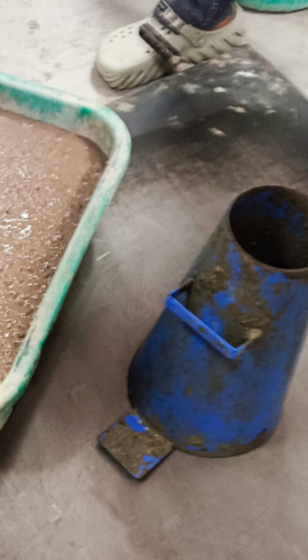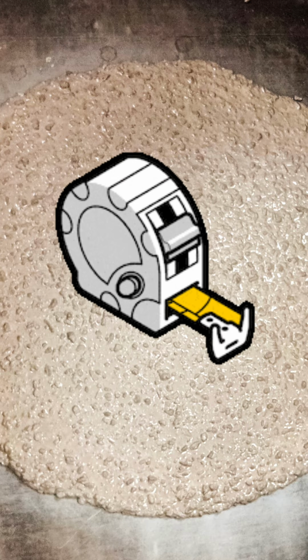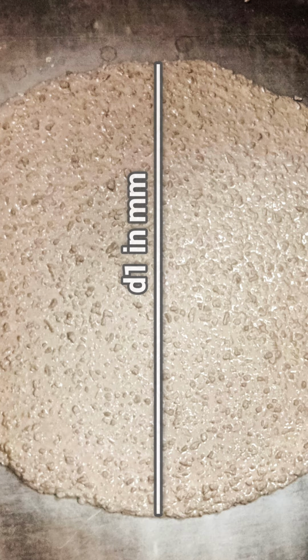Here we have placed the cone on the flow table itself. Then we lifted the cone in one go, and started the stopwatch from the instant the cone is lifted till the time the concrete touches the mark made to represent a diameter of 500 mm. When it touches that 500 mm mark, we record the time using the stopwatch, and we also note down the maximum spread to compute slump flow as (d1 + d2) / 2.